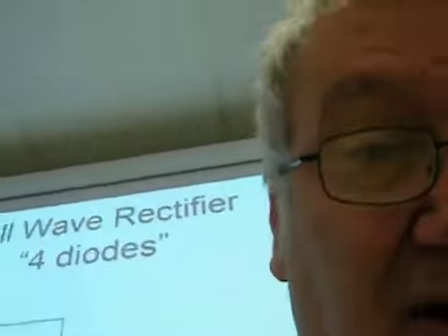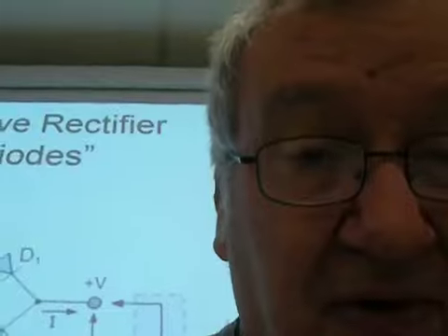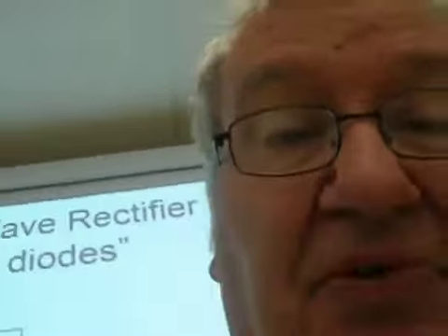When you're doing AC voltage measurements, remember the meter leads do not need to match colors. You just need to have one connected to one output, one to the other. In this case, I did match the colors, but I didn't have to. I could have hooked up the other way, and I still get the same result. And I'm reading 28.8 volts AC. So I know the power adapter is sending out AC voltage.